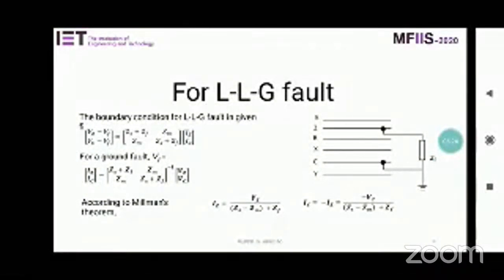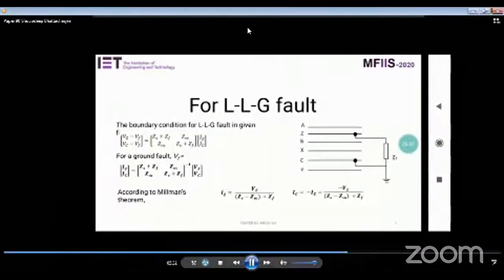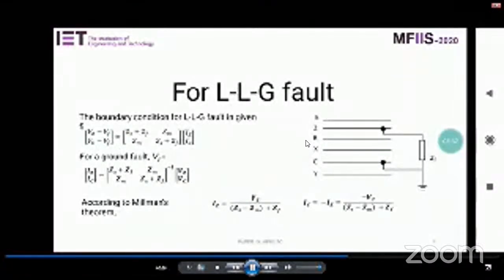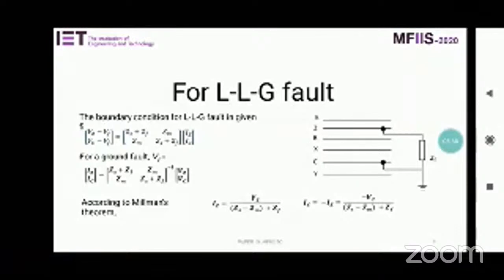To validate the proposed fault diagnosis method, a Simulink-based model of six-phase network is developed in MATLAB. Different faults are created externally, and for every fault condition, fault current data is measured for two different values of network parameters. In the first case, the six-phase network is supplied by a 100 kVA, 240 volt, 50 Hz six-phase alternator, and in the second case the six-phase line is connected with a 138 kV, 600 MVA, 50 Hz alternator.